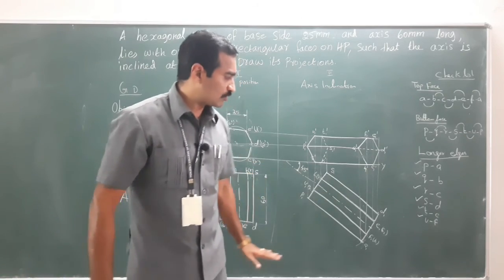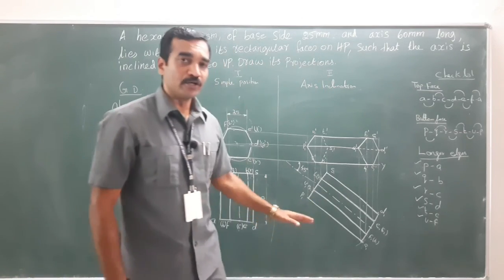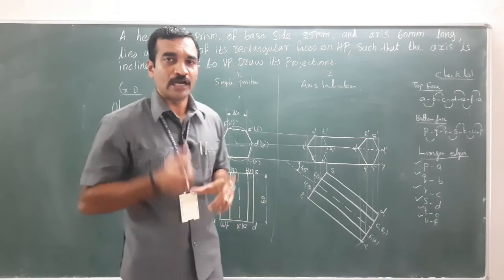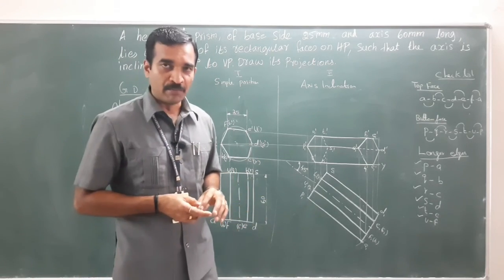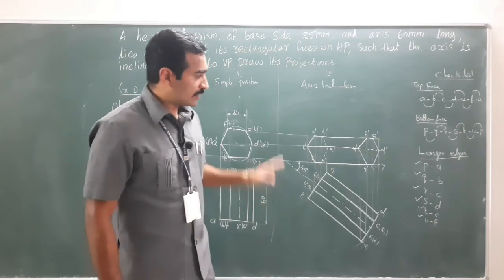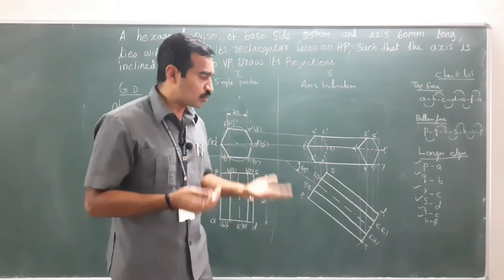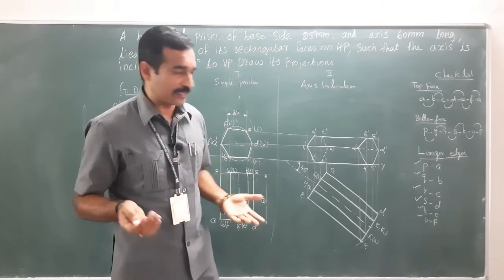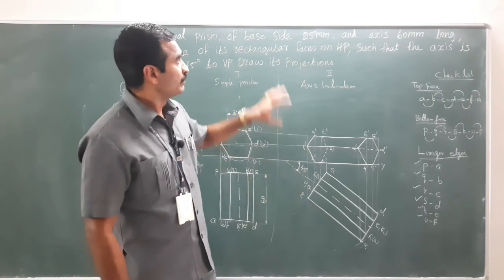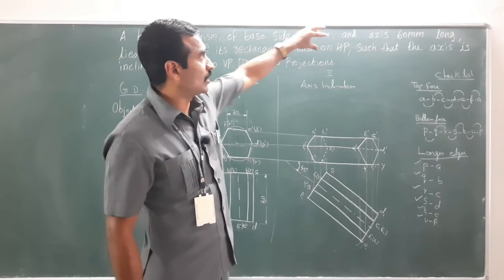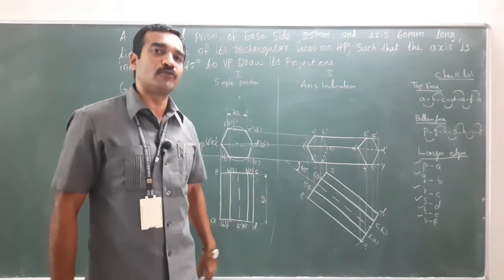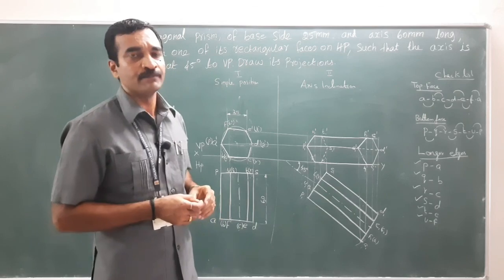Next, you will have to write the notes within the guideline of 5 mm height. You will have to mention all dimensions are in mm. And next, the scale you used, whether it could be true scale or reduced scale or enlarged scale. As far as this problem is concerned, I have used the original, actual dimensions given, same thing I used. Therefore, the scale could be true scale, which is scale 1:1.